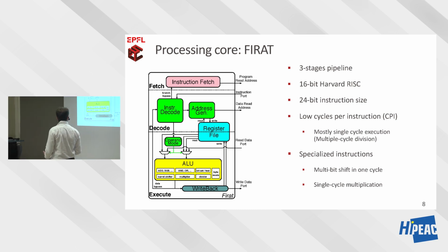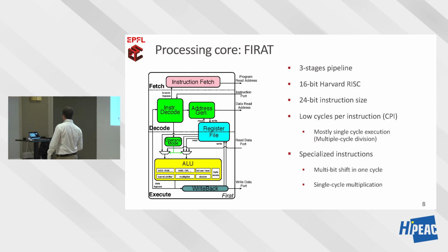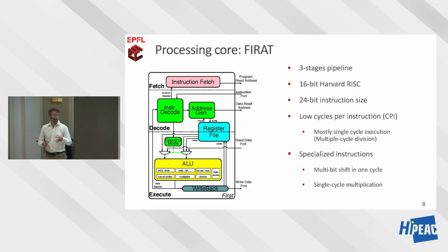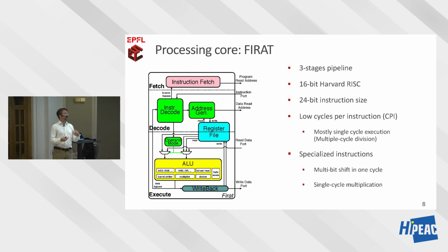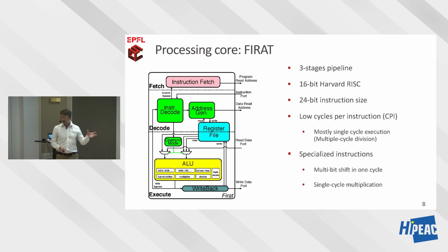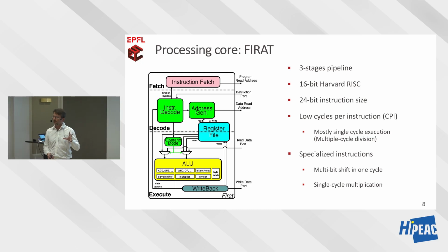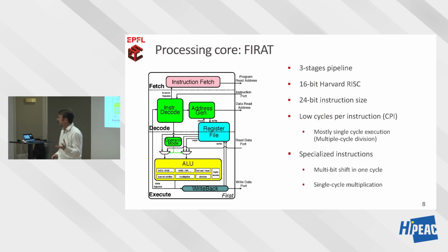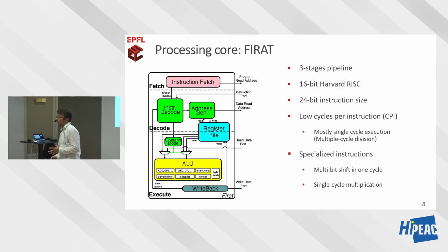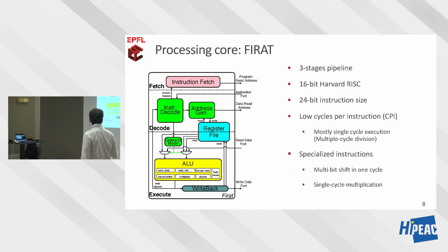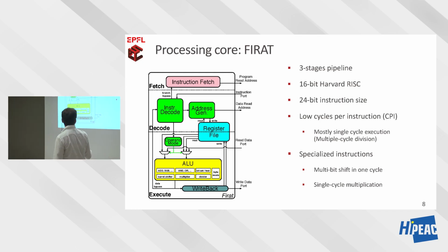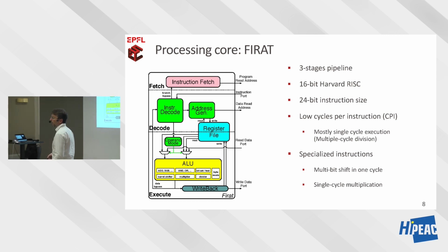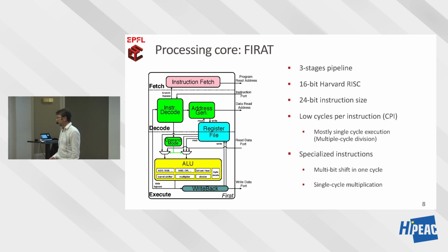What he aimed to achieve was the lowest clock per instruction possible. When you have this type of architecture, you are allowed to spend some of the real estate in order to specialize it a little bit. In this case, the specialization was very lightweight. We just wanted to support multiple bit shift in one cycle for the type of application which we wanted to run on this architecture.